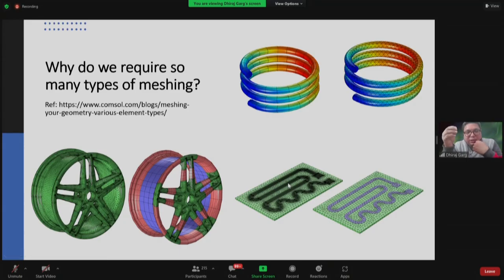But in cases where viscosity and density are sensitive to temperature, you need to model them as a variable of temperature. Accordingly, they will evolve with temperature, and flow and heat transfer will evolve accordingly. So it will become a coupled problem, heat transfer and momentum transfer, and it will consume more time despite having the same number of mesh elements and everything, to evolve into the right solution. I hope that is clear, or if there is anything I can help with.